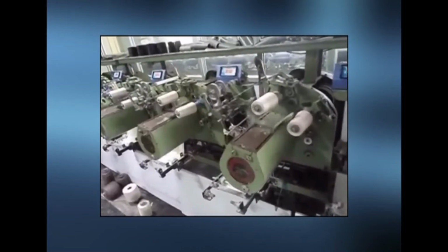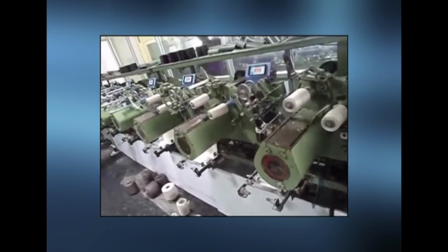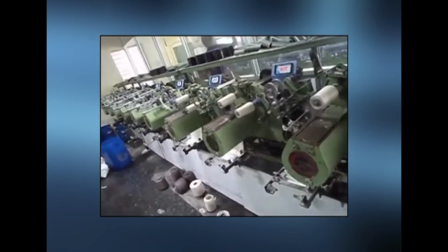So, many fibers which are available in the market today are either man-made or synthetic, except those which are available in fiber form, especially the natural cellulosic or protein fibers like silk and wool. They are all available in the form of fibers, whereas nylons, polyesters, polypropylene and all other fibers are not available in fiber form. And so, the chemical spinning is applicable to these fibers, because the manufacture of the fiber is also involved in it. All these fibers are mostly filamentous in nature because they are manufactured as filaments.